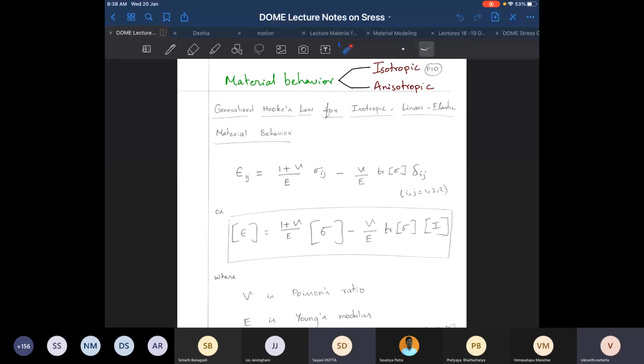We don't want permanent deformation of the design of the machine. Very good. So we do not want any of the machine elements to undergo permanent shape change. When they are subjected to loads, we only want them to undergo elastic behavior. So we are going to work with the assumption that behavior is elastic, and we will see when it will turn into plastic.